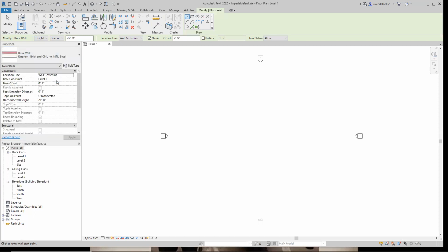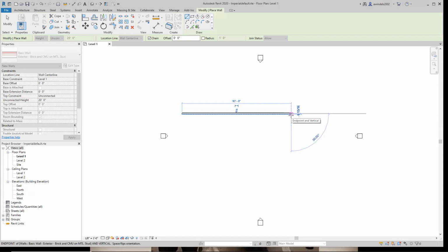But for now, let's start by just talking about the interface, okay? And I'll get into that later. So we've now selected our adjectives, what we want it to be, this type of basic wall. I'm just going to draw this quick. Here to here, I'll snap it. Revit likes to stay tangent and increments by default. So that's helpful when you're drafting. I'm going to hit escape. I'm going to accept that wall. I have one element now.